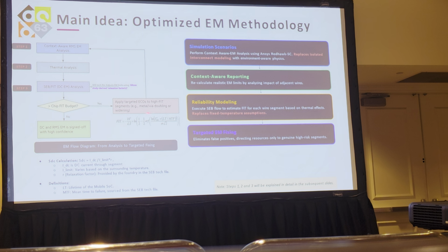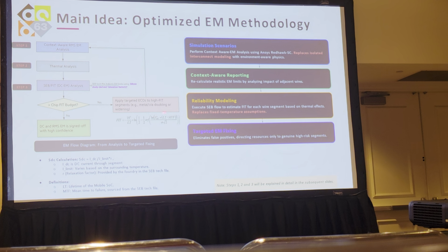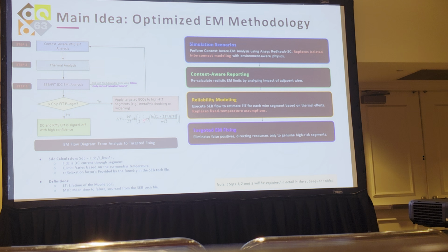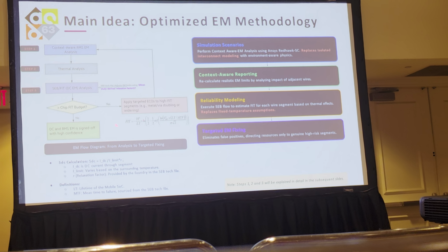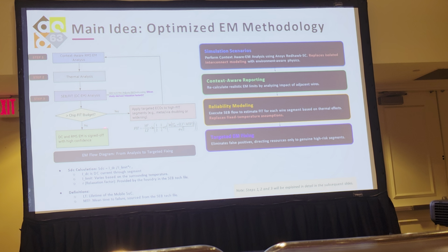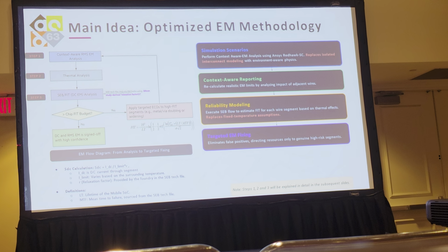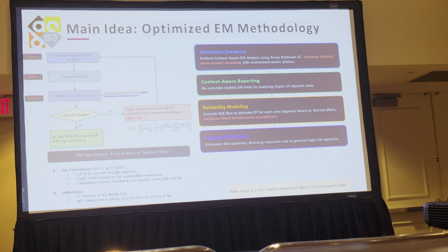Here the SDC is the EM percentage that we calculate in the context-aware flow, and LT is the lifetime. Based on these parameters, it calculates the FIT value for each and every interconnect, and the higher the FIT value, the higher the failure rate.